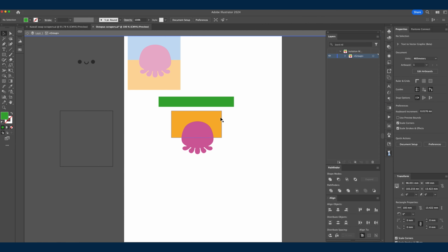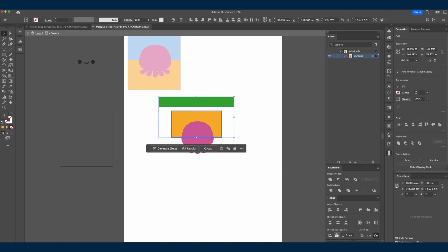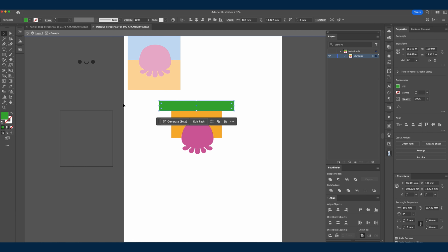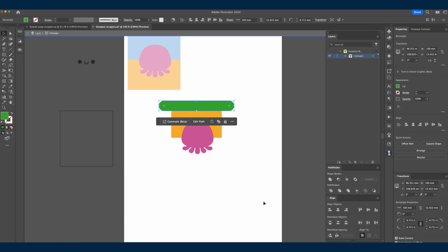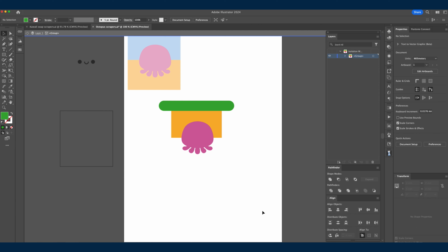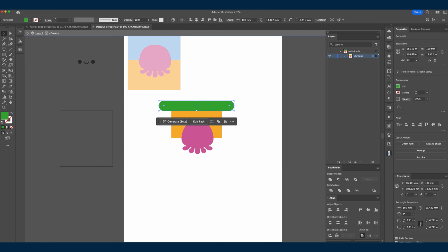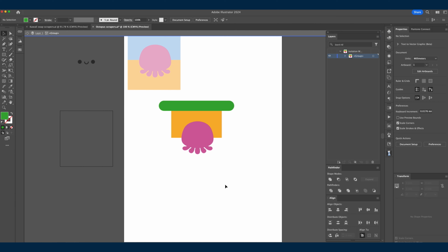I want to make sure that between those two, I have a gap of 0 mil, and that they are aligned centrally. Then I am going to curve those edges off. So I know that the width of this is going to be 100 mil. That's really important later on when we move into putting this into our 3D modeling software and then into our slicing software. We're going to want to scale this up a little bit so it does fit. So as long as I know that measurement is 100 mil, I can make sure that works.